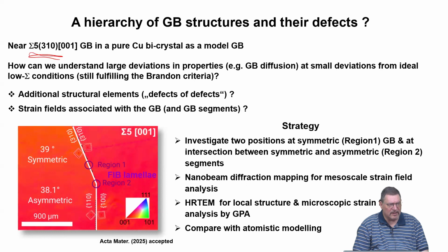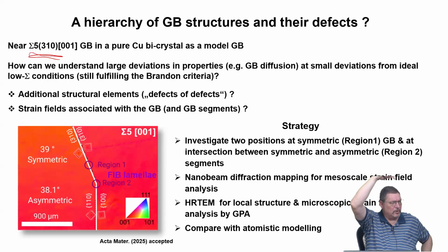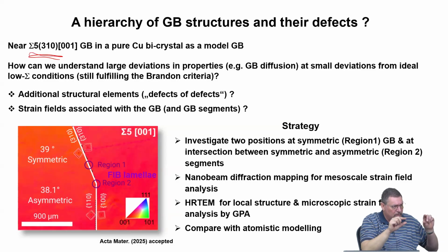And this is the EBSD image, so electron backscatter diffraction. You know also what it is? Okay, it's a scanning electron microscopy based method where you basically look at the signal of electrons which have been emitted by your electron gun, by your cathode, and which have been backscattered from a very thin region of your crystal into a detector which is situated at a certain angle.